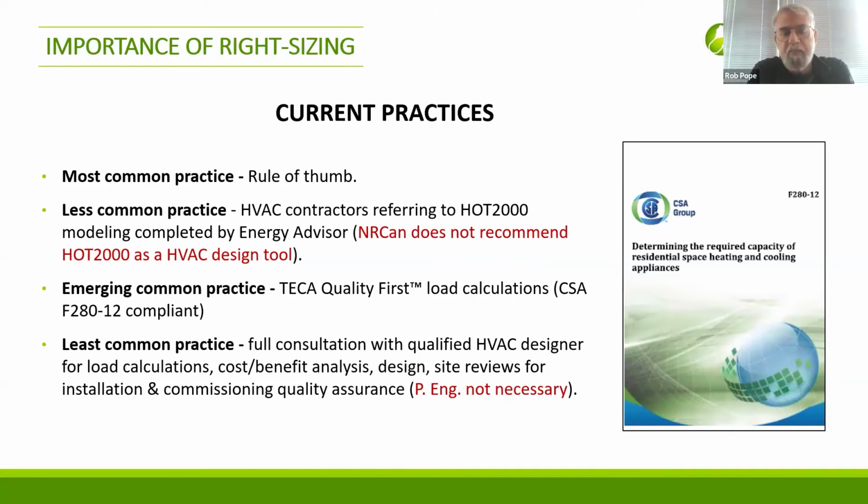Less common practice: HVAC contractors referring to HOT2000 modeling that's been completed by an energy advisor. Now, NRCan does not recommend HOT2000 as an HVAC design tool. We'll get into this later, but you can use HOT2000 output for a block load, especially for a retrofit, to align what your assumption is, or what your own load calculations have told you is the heat loss of the building.